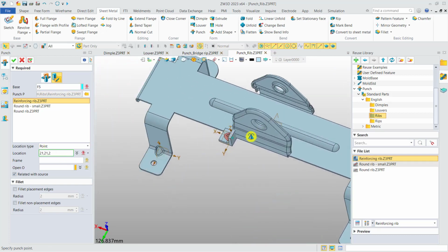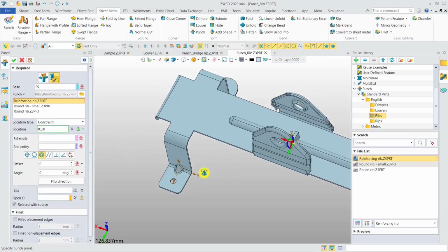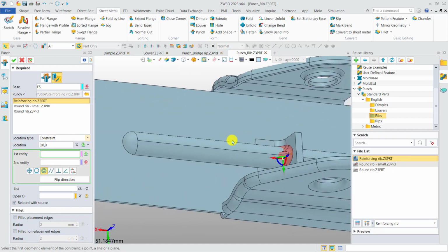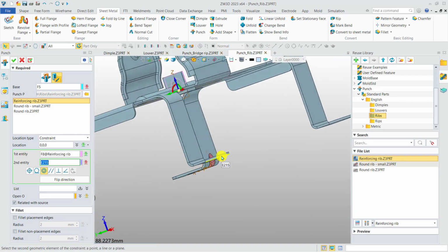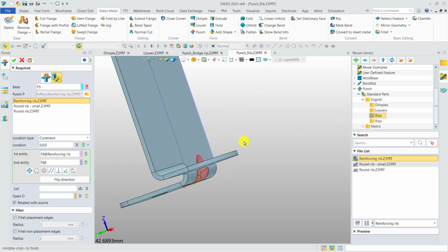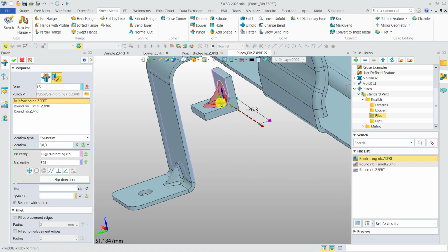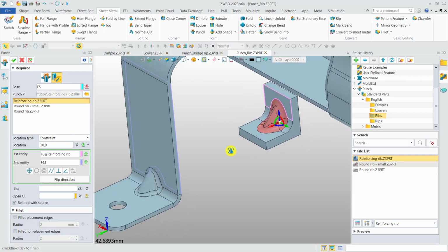And we need to make the position right. Okay, now you can see something like that. And we can choose to use constraints similar to the constraints in the assembly environment. First, we choose two planes to be coincident. Okay, and we can drag it to the position we want. Now it's already constrained, so it cannot be dragged.